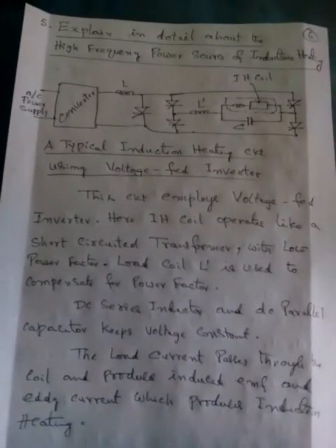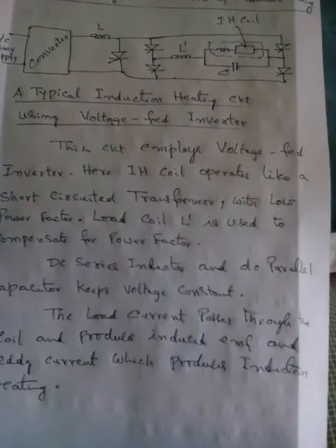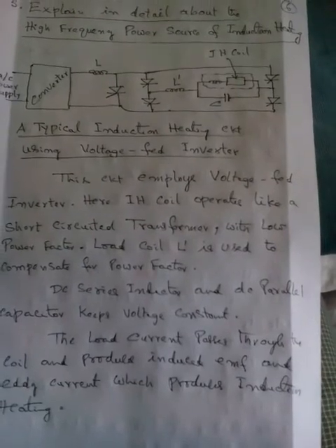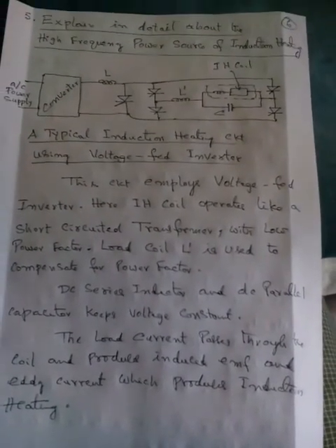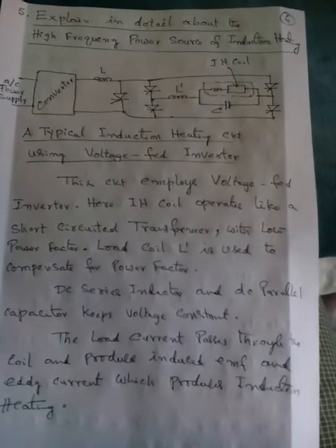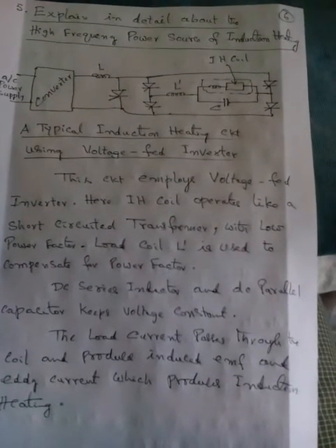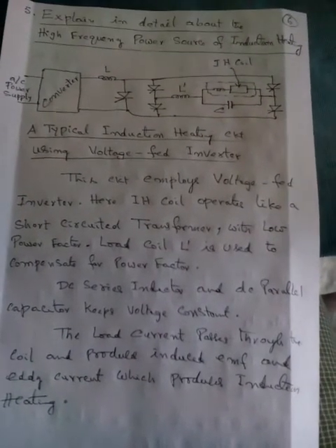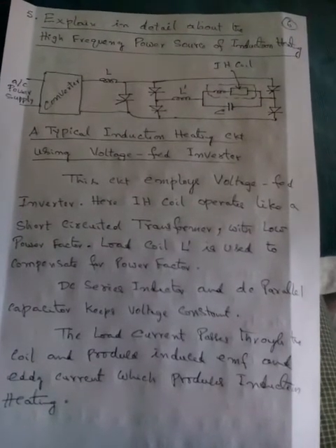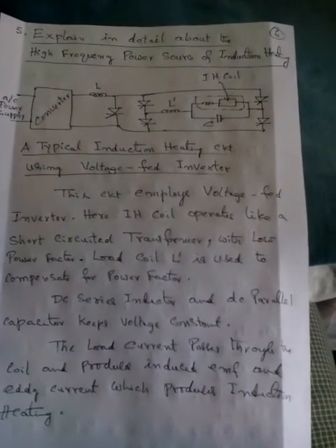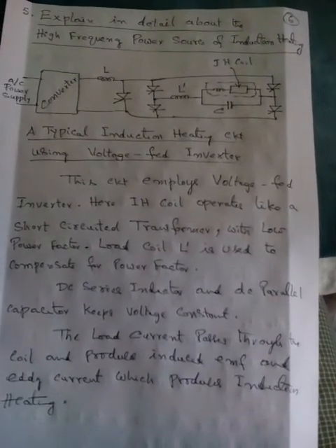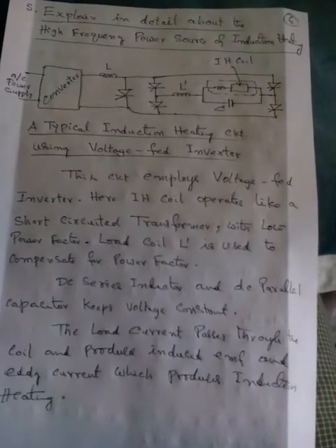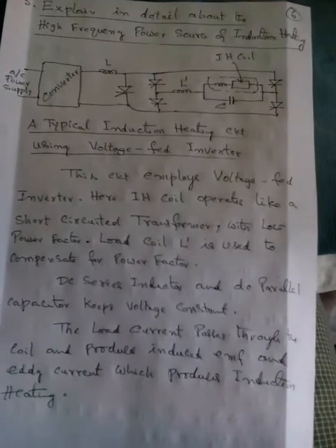The load current passes through the coil and produces induced EMF and the eddy current, which produces induction heating. This is of course a very simple but very effective method of producing induction heating. It is also very frequently asked to explain in detail the high frequency power source of induction heating. This is a commonly employed heating arrangement in the industry, the typical induction heating system using a voltage fed inverter.